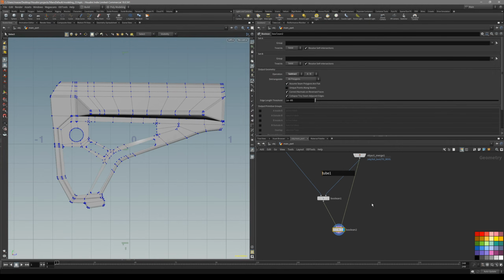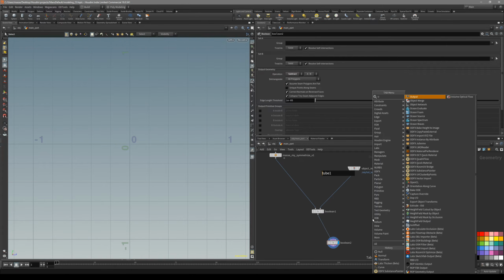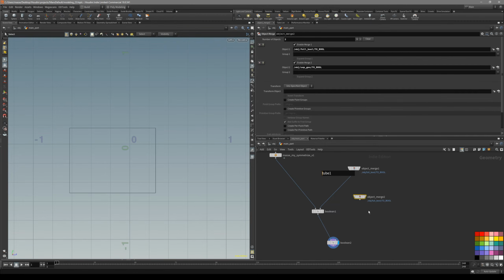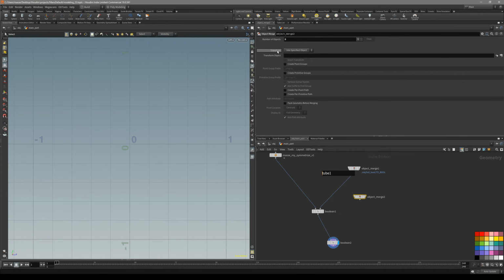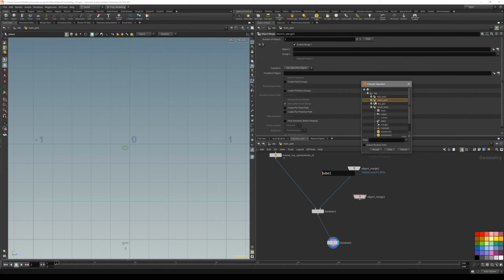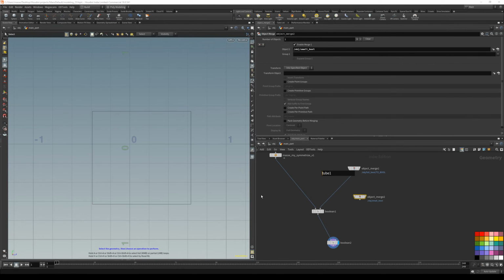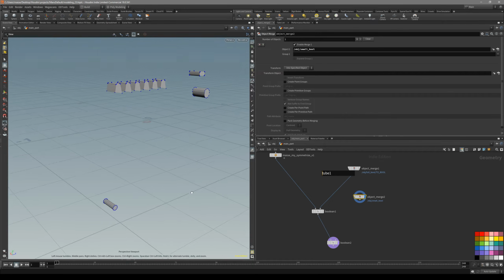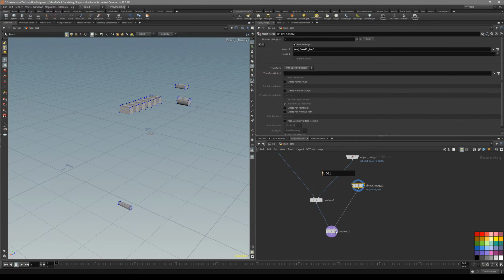So let's go to our big model, and let's create another boolean. Just duplicate it in here, object merge it. Let's just copy this one also with alt drag. Let's delete these. Let's add a new object, and let's reference the entire geo node that we have, the small bool. You don't even have to reference any particular node, since you want to reference all of the geo node. Just double click it and that's it. Now we have brought this one up, and let's boolean it.